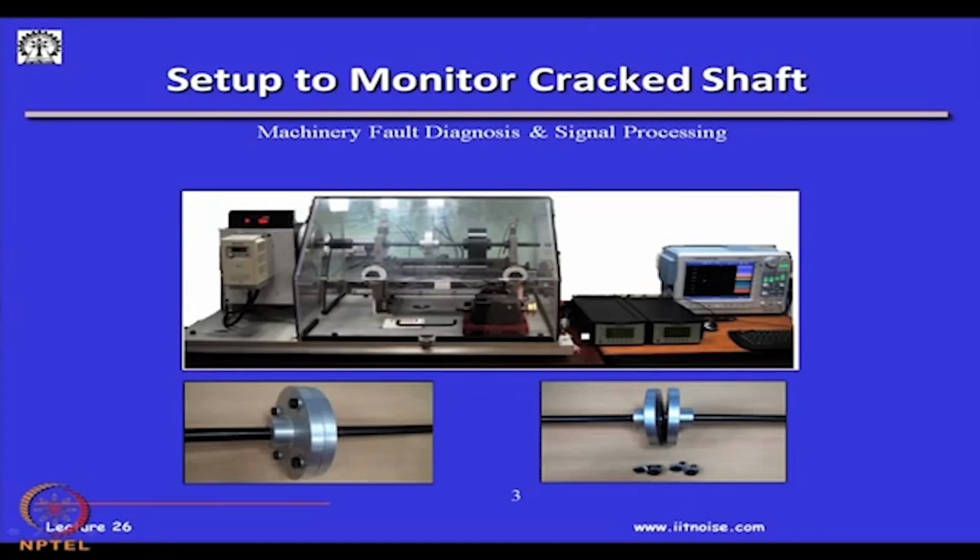Okay. And what we do here is, again, when we have a crack shaft, we always measure at the bearing locations. As I told you beforehand, in condition monitoring, usually when you monitor rotating machines, this is the only good place we have to keep the transducers, and here also we have to keep the transducers on these 2 bearing locations. And this black disc here is actually a loader. It's a heavy weight which is rotating along the side of these cracks. So, that this is responsible for giving that load, bending load which is coming down, and which will be responsible for opening and closing of the crack and create this breathing mode.